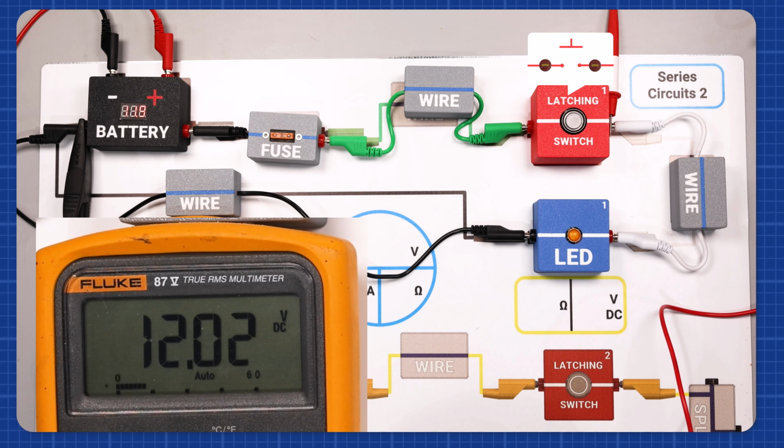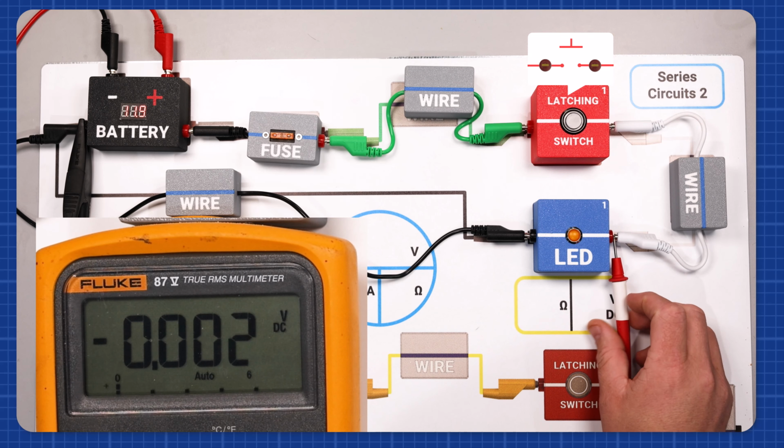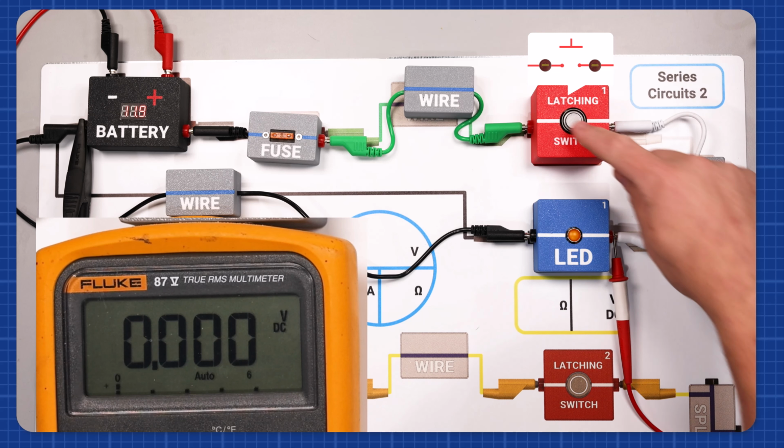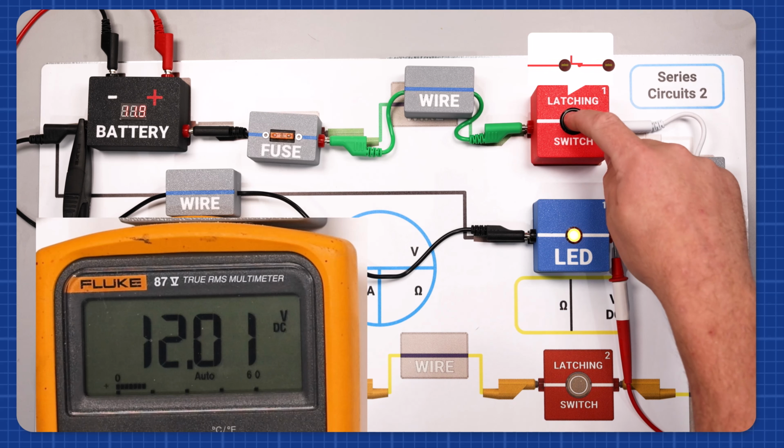Step 5. Measuring voltage at the white wire leading to the LED. At the white wire leading to the LED, the voltage reads 0 volts with the switch open. Since the circuit is not complete, the potential difference doesn't reach this point. When the switch is closed, the voltage at the white wire now reads approximately 12 volts. This confirms that the potential difference has reached the LED.